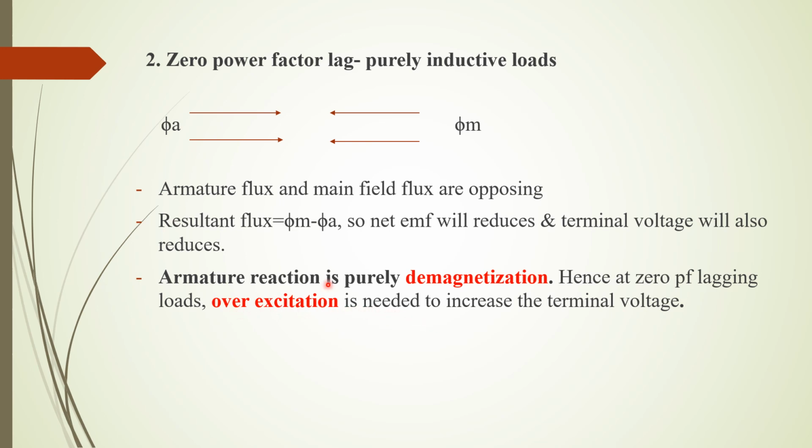So at demagnetization effect of armature reaction, overexcitation is needed for the alternator when purely inductive loads are connected to it. So these terms are very important.